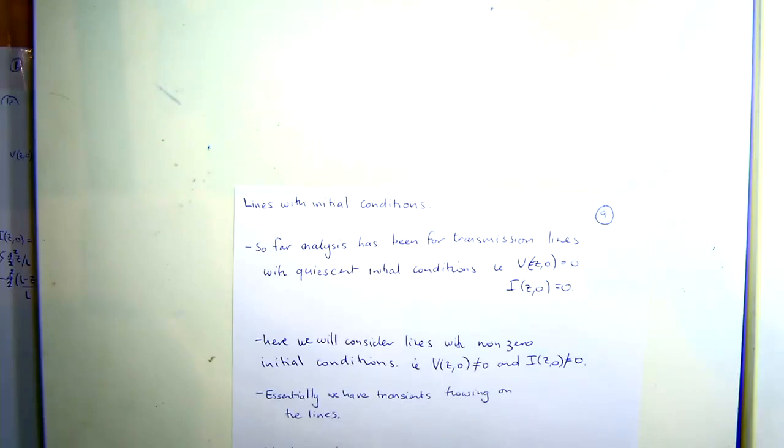depending on that length, or the time it takes for the wave to go from one end of the transmission line to the other. So you can actually make a pulse of tens of picoseconds, right? If you've got 10 kV here over 50 ohms, what's the current going to be? 200 amps. So you're getting 200 amps across this line over 10 picoseconds. So you've got this very sharp pulse that's gone through, right?